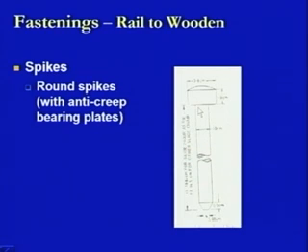When it is inserted into a hole, it works like a bolt. So, the top of the bolt is like this only, abutting the surface so that it remains in place. The hole will be in the bearing plate as well as at the foot of the rail section, through which it will pass and fasten the rail with the wooden sleepers.